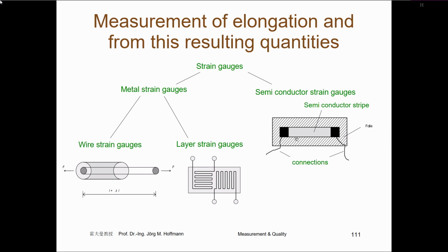And therefore, for semiconductor strain gauges, we have to additionally measure the temperature. We have to calibrate each strain gauge differently from the others.